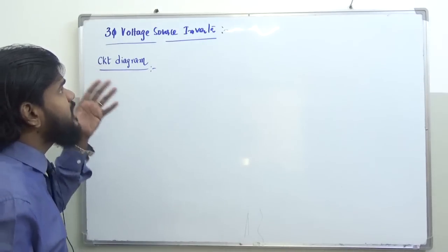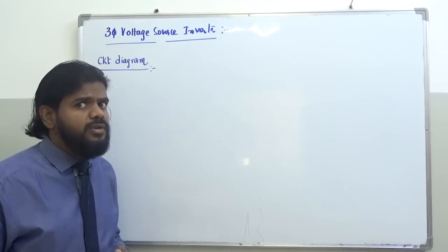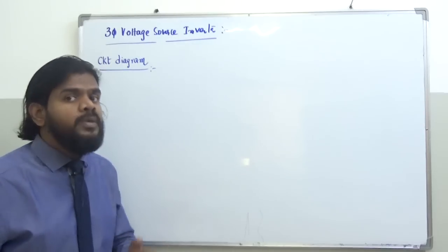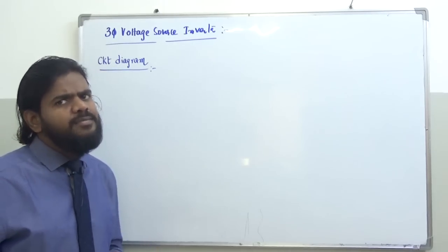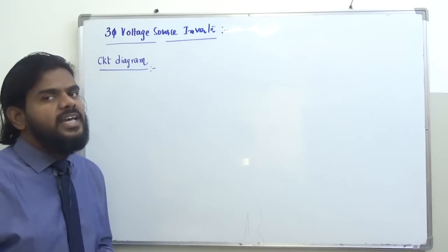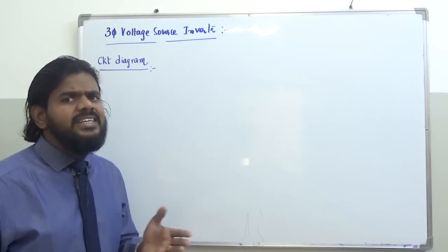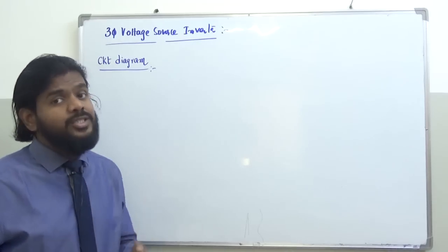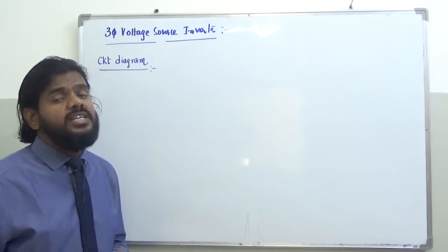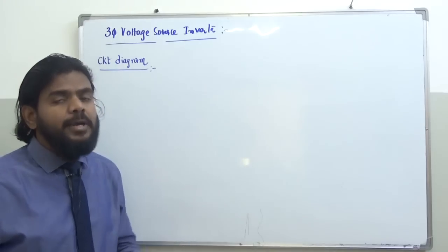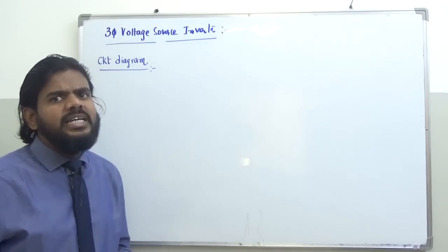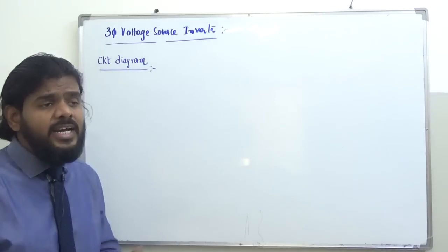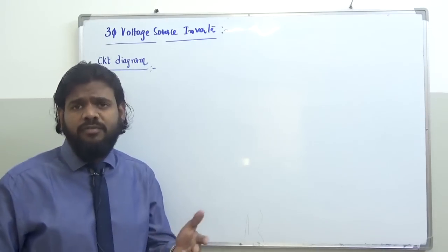That's okay. That's a general introduction about the converter which is called an inverter. And coming to this specific type, the voltage source inverter, this is a 3-phase voltage source inverter, which is going to convert DC voltage into 3-phase AC voltage. Very simple. DC voltage is taken from a battery and given to the converter configuration, which is the voltage source inverter, and by having proper switching action, you can get a 3-phase output voltage. You can have phase A, phase B, and phase C.